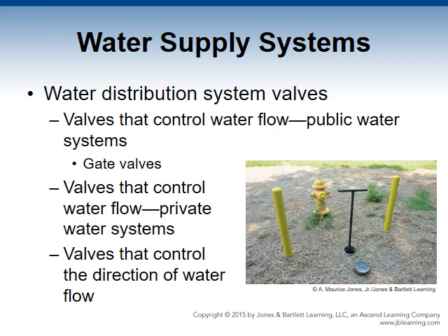Post indicator valves, abbreviated PIVs. They have a freestanding post that houses the stem extension of an underground valve. They indicate the position of the valve through a window on the post with the words open or shut. If one of the words is fully visible, then the valve is fully in that position. Operation of the valve requires a special wrench that is attached to the top of the valve nut and hangs down the side of the post. Often, this is secured with a lock.